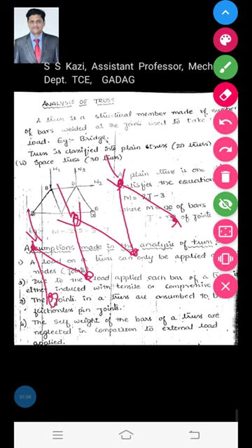And due to the loads applied on the bridges, the truss structures, each bar of a truss is induced with either a tensile or a compressive force, that is, each bar either expands or contracts due to the load applied on a truss member. Hence a truss is also called a two force member.